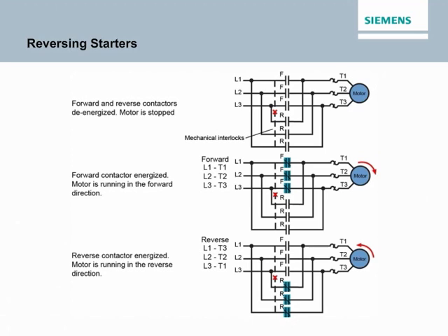Mechanical interlocks prevent both forward and reverse circuits from being energized at the same time. Siemens offers Class 22 reversing starters and Class 43 reversing contactors in NEMA sizes 00 through 8, including Siemens half sizes. Class 25 and 26 combination reversing starters are available as well.